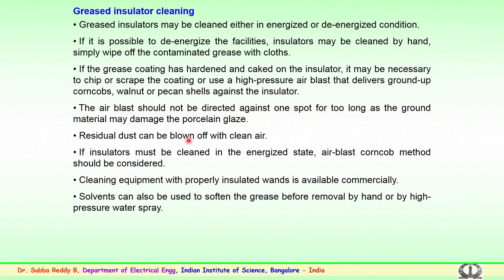Some solvents can also be used to soften the grease before removal by hand or by high pressure water spray. So, several techniques or methods are used to clean greased insulators in the energized or de-energized condition. Proper care has to be taken, so while removing the greased coating, surface damage to the insulator should not be done.